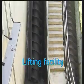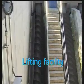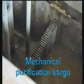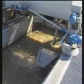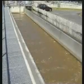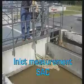Before the wastewater runs through the individual purification stages of the sewage plant, it is raised by a pump to a level that guarantees the free flow of wastewater through the plant. In the mechanical treatment phase, coarse solids and hygiene articles are removed from the wastewater by a bar screen. In the next stage, the aerated sand trap, mineral solids and fats settle out of the wastewater. The first process measuring technology to give an indication of the composition of the wastewater is found here in Langen at the outlet of the sand trap, even before the biological treatment stage.